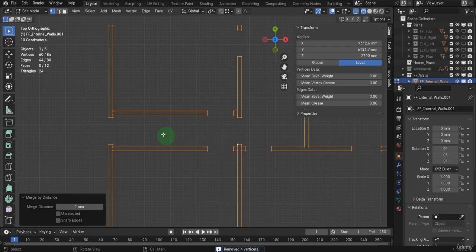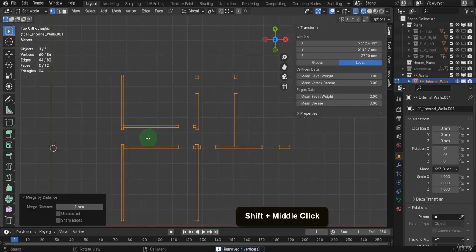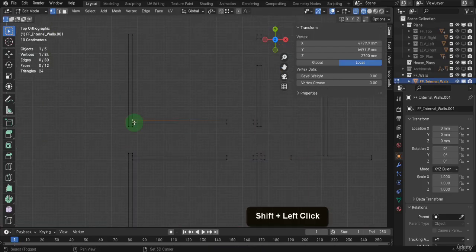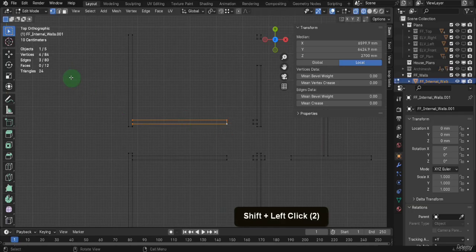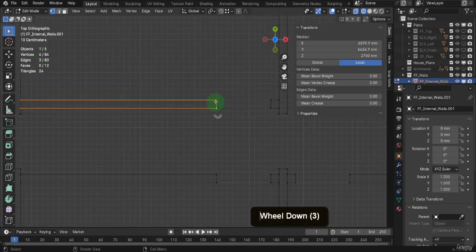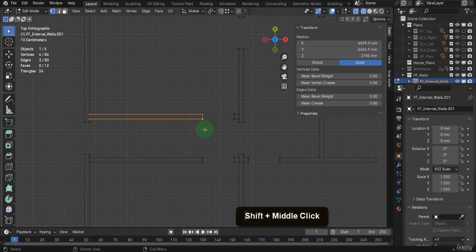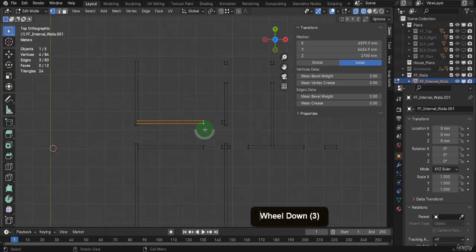Now we can start selecting 4 vertices. Keep an eye on the number of vertices if drag selecting, as there may be extra unconnected vertices that get selected. Delete them if you come across any. Press F and create a face. I can quickly work around.